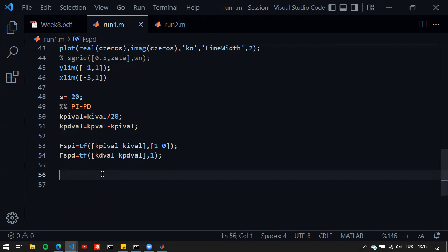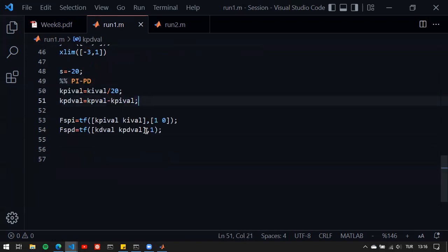It has a multiple feedback loop structure that you should memorize, for example, in this case, because you have to be careful about the fact that the PI-PD controller is not using one loop, it's using 2 loops here. One to use the PD controller and then an outer loop for the PI controller. That's really important here. Now here, according to the closed loop transfer function, we've seen that in run 2 that the sum of them is equal to the proportional part of the original PID controller if you're using a base PID controller. Now, once we've decided on that,